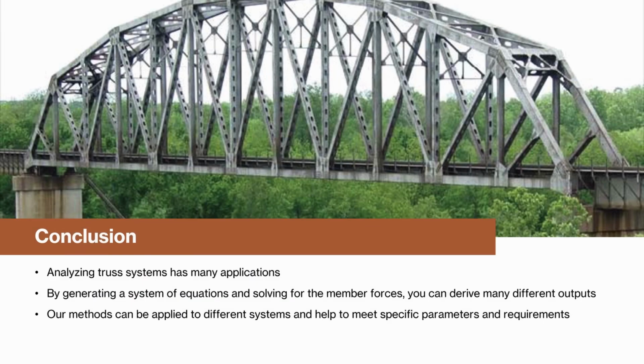In conclusion, analyzing truss systems has many applications. By generating a system of equations and solving for the forces in each member, we can derive different outputs, like the cross-sectional area, the stress, and the displacement of each member. Normally, if you were to compute this by hand, it would take a very long time. But using Matlab, we're able to compute it in a more efficient way.